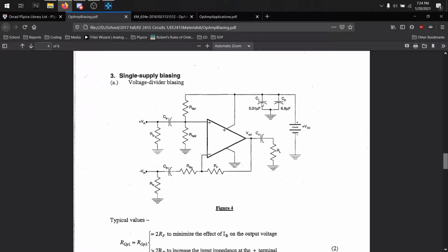Do you mind if I jump in a little bit for that part? Yes. So as Bryce said, it does filter out noise, and I guess what he means by that is, let's say, high frequency noise in that voltage source. They get shorted to ground, so you would place those capacitors close to that battery. So that's what they do.